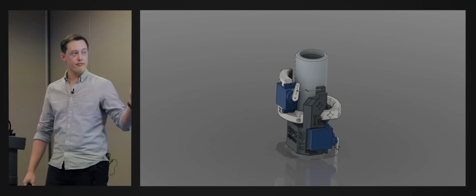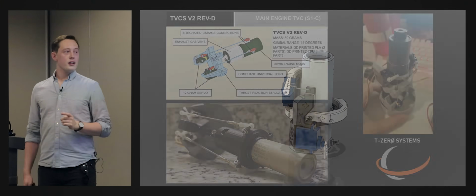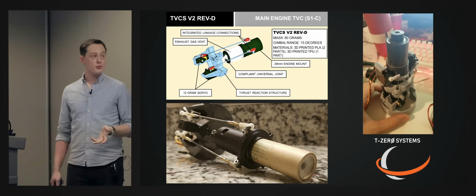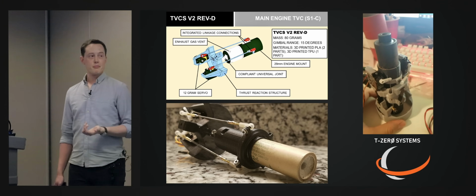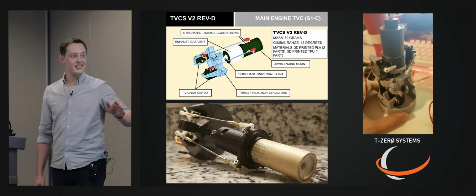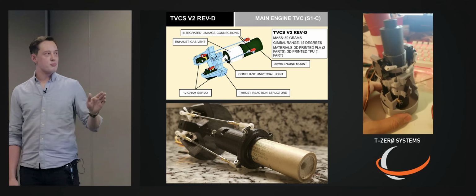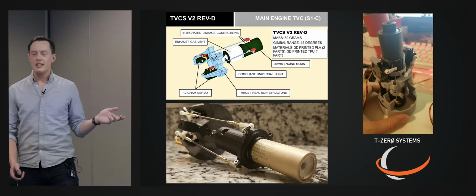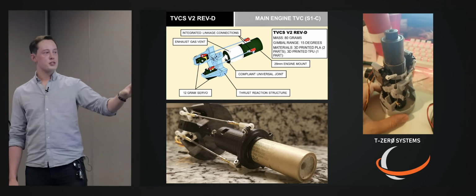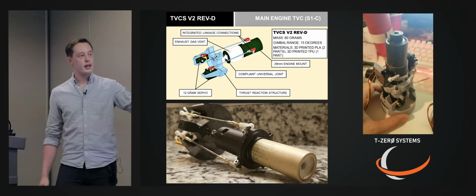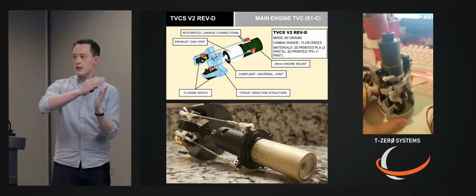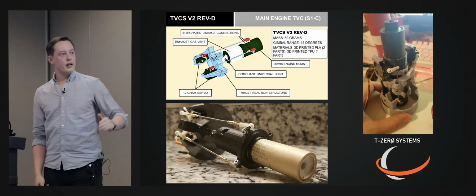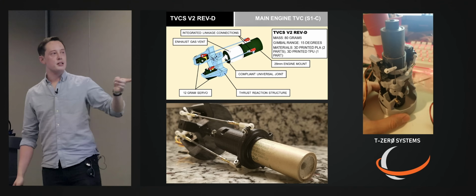But this is by far not the only way you can do it. My friend Rob, again, it's cut off a little bit, is an actual orbital launch vehicle engineer down in Cape Canaveral. He really knows what he's doing. But he's got a couple of different setups as well. So his thrust vector control approach uses, it's not technically linear actuators, but it's actually quite close to how you would gimbal a liquid engine, in that you've got 2 orthogonal, or 2, 90 degrees apart rods that come down on the motor. He's also got a compliant gimbal, which once again, it's a little hard to see here,